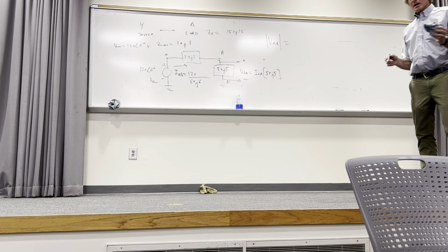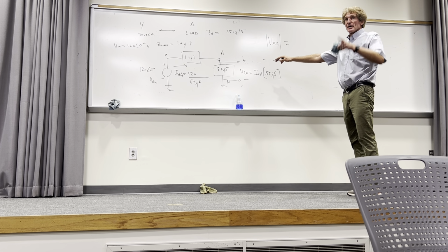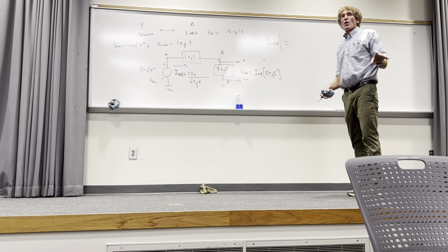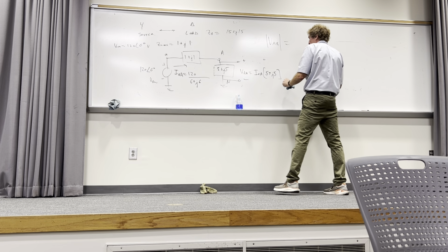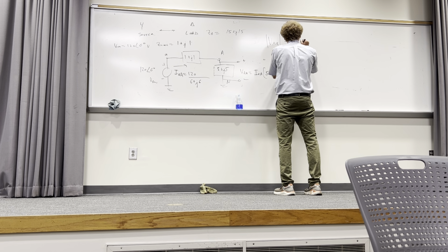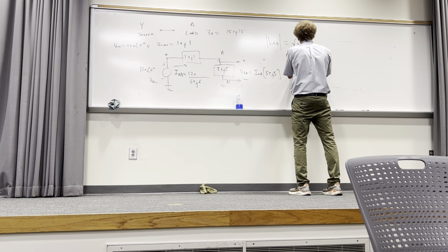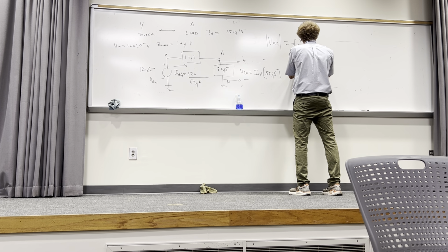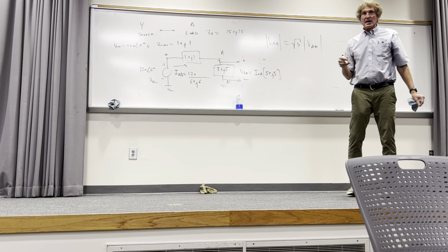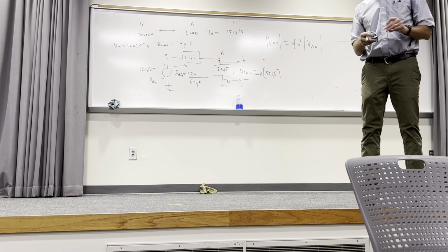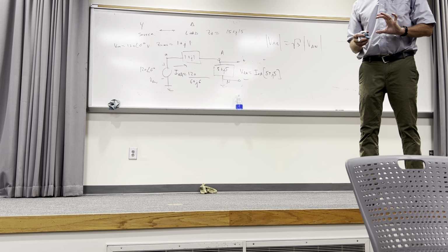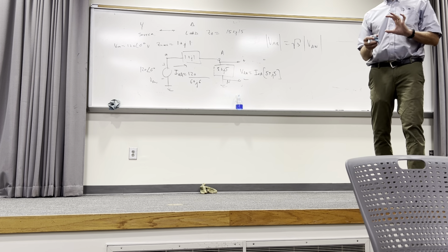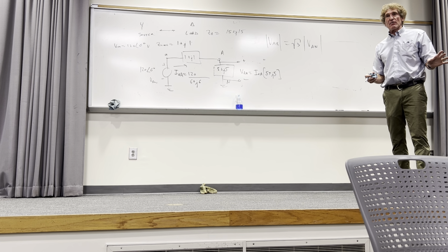All right. Now, can you say it or not? Over here, guys. If you want the magnitude of V cap A, cap B, right here, you would take the square root of 3 times the magnitude of V cap A, cap N. Do you all follow me on that? So it would be the voltage developed across the load, the A, capital N, load, times the square root of 3. Everybody with me? Now the angle would also be advanced by 30 degrees, if that was asked for.